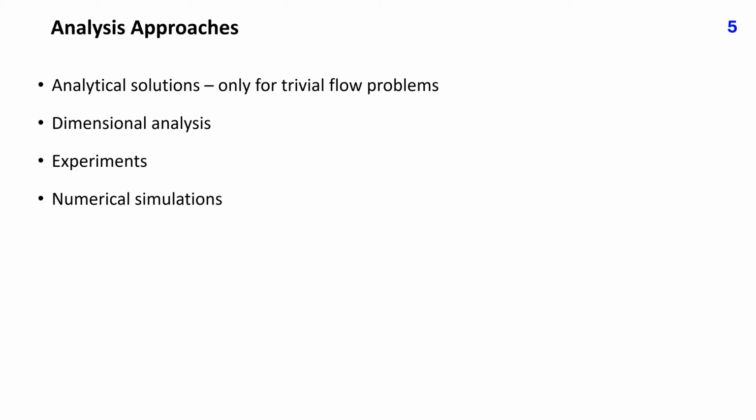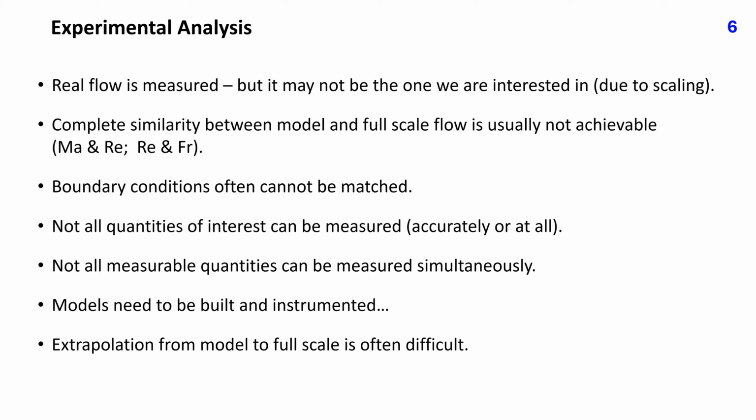Experiments are still widely used to perform testing of products prior to their release to the market, but numerical simulations are gradually replacing experiments in many situations. These two approaches will therefore be discussed in more detail in the following slides. In an experiment, a real flow is measured, but it may not be the one that we are interested in. In most experiments, the objects are scaled down and there is a significant uncertainty in extrapolation from laboratory to the full scale. A complete similarity is seldom possible.